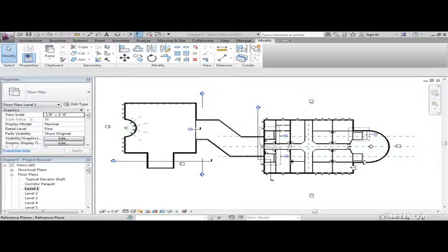In this lesson, we'll be using the Align Dimension command. Here's where we find out if anything we did at all is accurate. It's dimension time. Dimensions in Revit are just as much of a tool to help us lay out a building as they are a means to convey information to the people reading your plans.